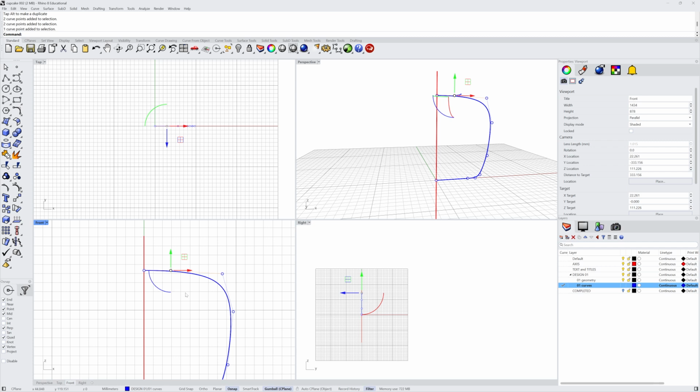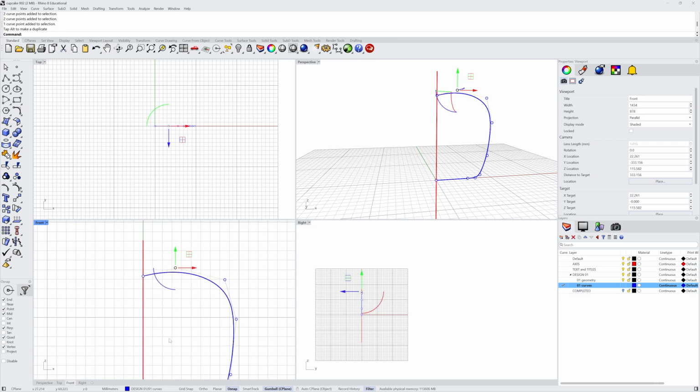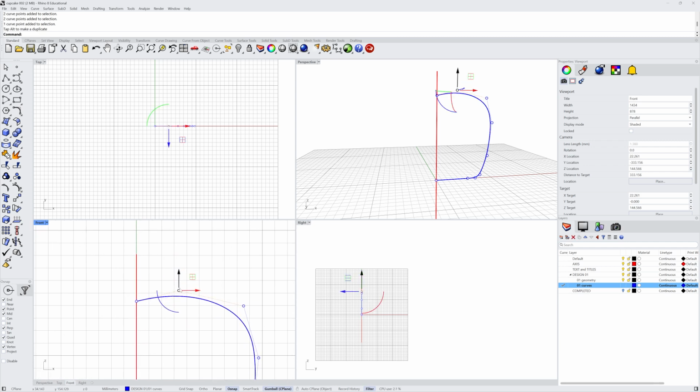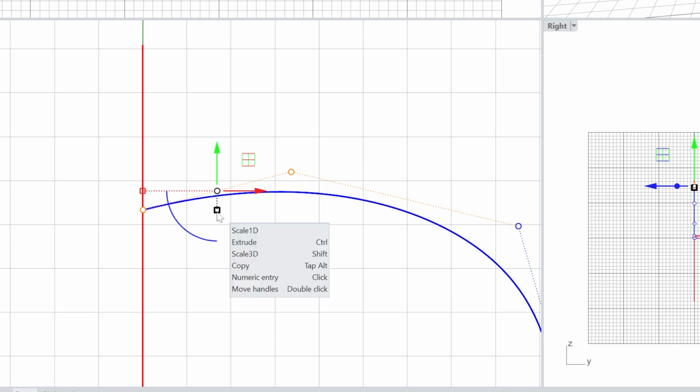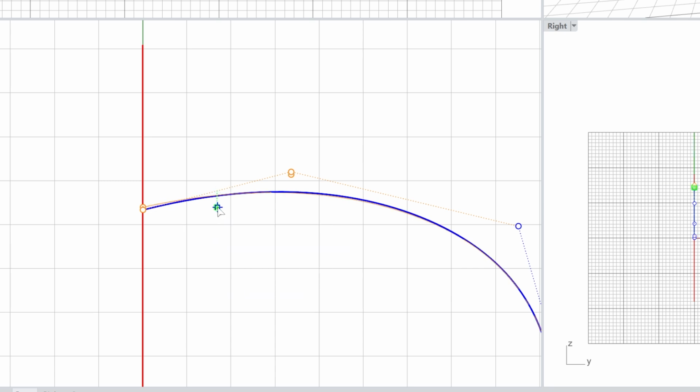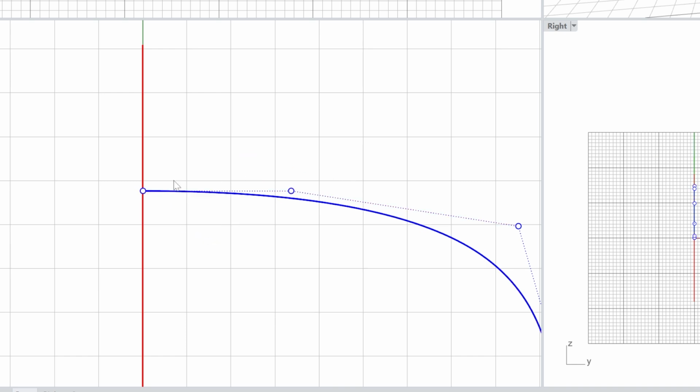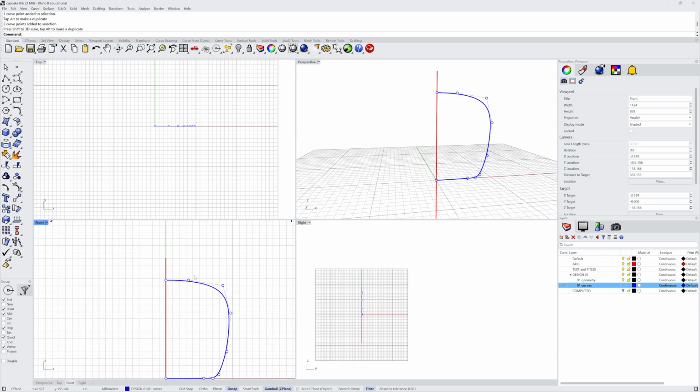Now, if you accidentally move them away, here's a great little trick I use. Let's say it's coming down at an angle. That would make kind of a little hole or divot or pinch. So you can pick both of those points, and you can scale on the axis where you want them to align. So I'm just going to hold down that gumball square, and you get a little point snap. So those two are now perfectly aligned. It's a great way to do it.